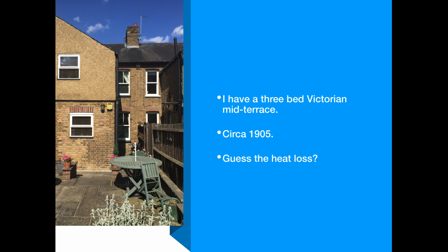Now you've all got these in your mind. I can't do live situations here, but this next slide actually shocks quite a few people. That's the actual, calculated heat loss for my house. Now the problem is, at the moment you can't buy a boiler small enough to match that. That heat loss calculation is based on a London outside mean temperature. I'm in North London in Rickmansworth, an outside mean temperature of -1.8.